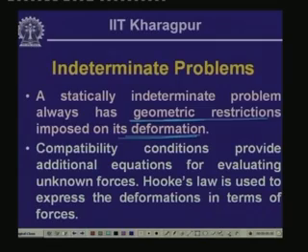So, we have seen that we have 3 equations of equilibrium, which are statical equations of equilibrium. Over and above, if we write down the equations of compatibility which arise from these geometric restrictions for the deformation, this equation of compatibility along with the equations of equilibrium will lead us to the system of equations from which you can solve the unknown reactive forces in the indeterminate system. So, now you can distinguish between a determinate system and indeterminate system.